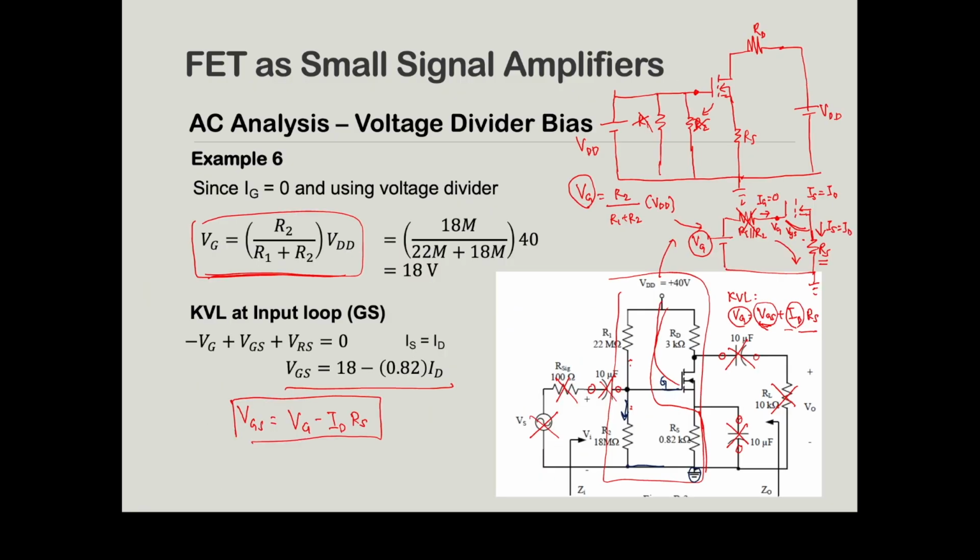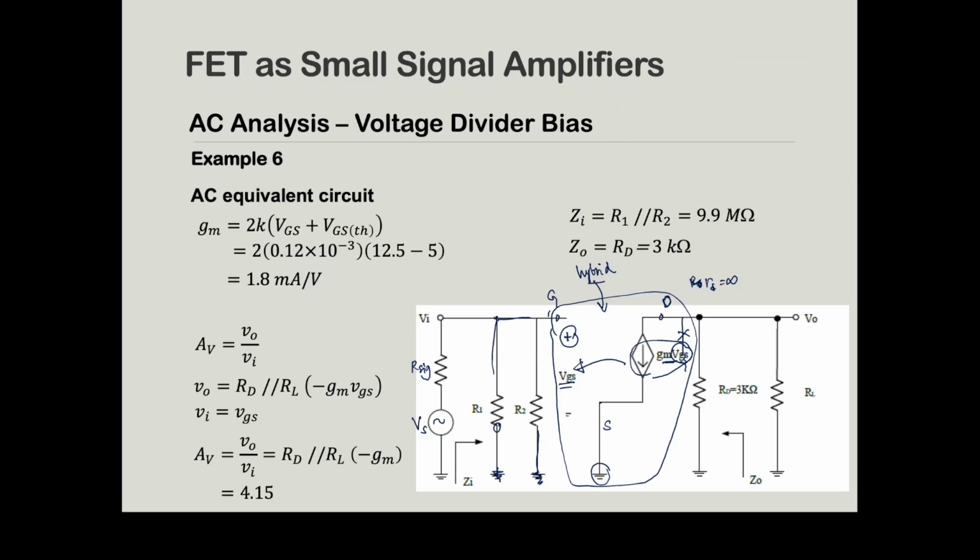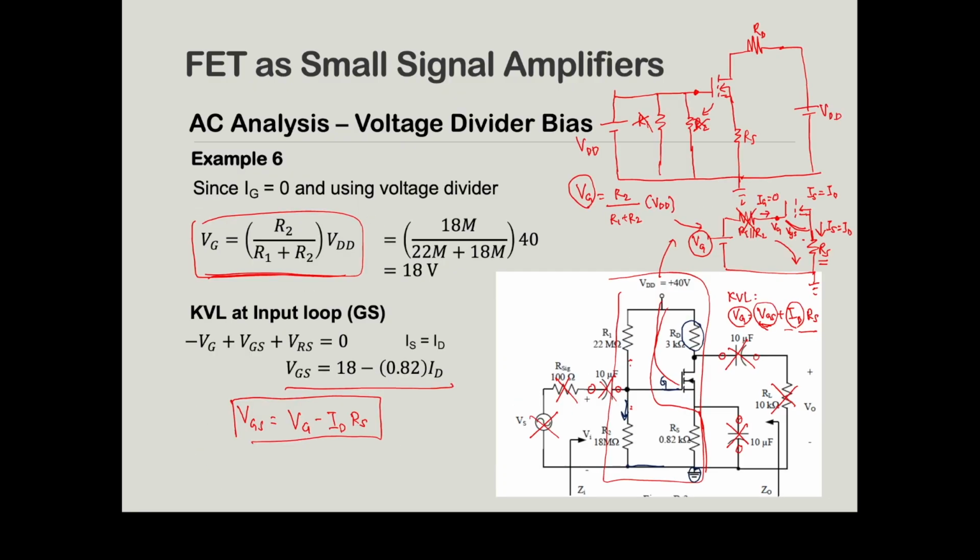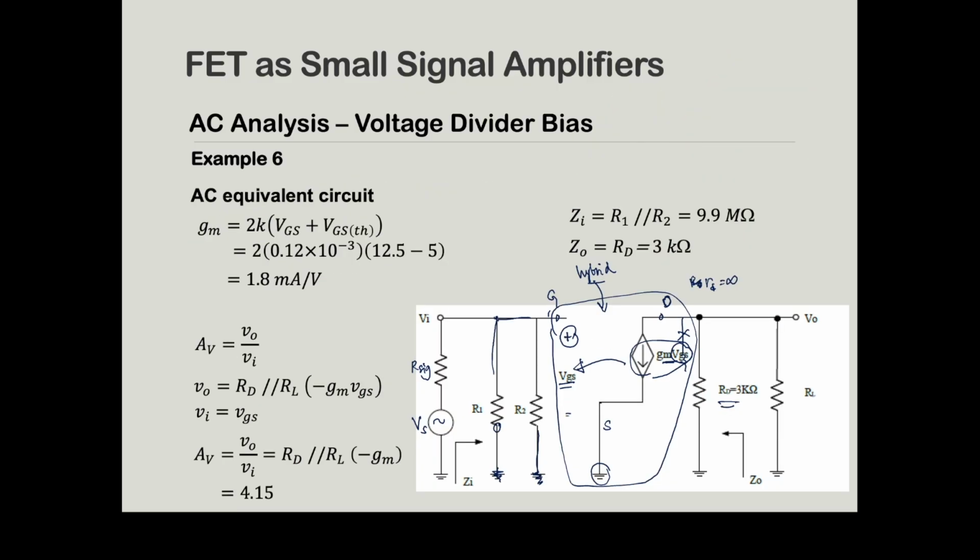Next, at the drain terminal, we're going to have this resistor RD, and then you're going to have RL. Across RL we are measuring the output voltage, Vout. This is positive, this is negative. And don't forget to label your impedances. Sorry, this is the output impedance and this is the input impedance.